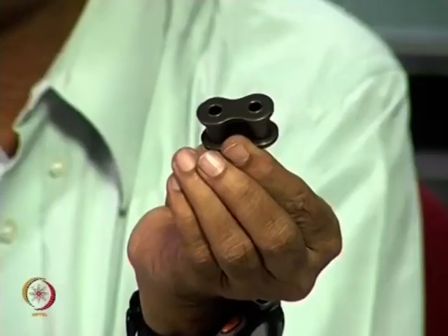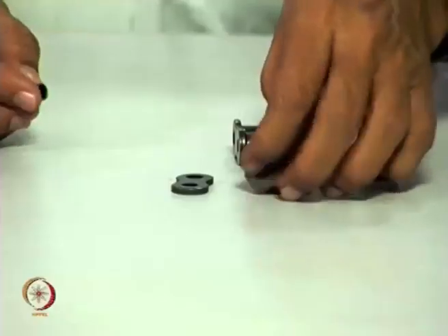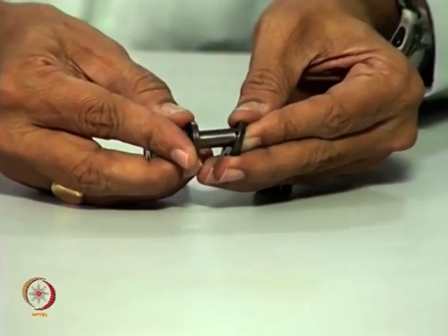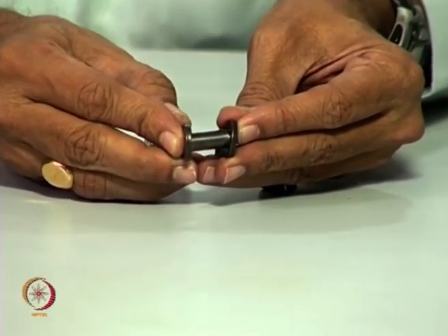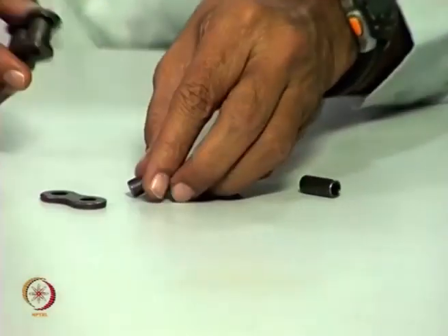See, you have to know how this component is fabricated. Suppose I take a block of material and then I go to CNC machining and machine this out, that is one thing. And how it is done is you have essentially plates, and these plates are brought together by putting the appropriate bush, and the bush has to stay in place. So, you have an oversized bush and this has to be inserted.